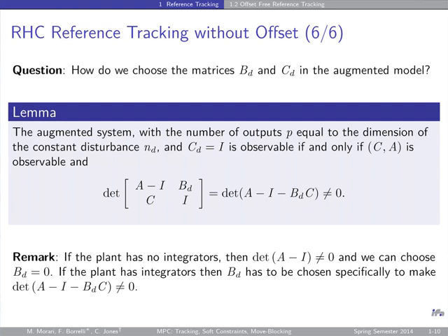The only disadvantage for some computations of this penalty function is that it has this kink, as you saw. It has a corner down there. For optimization and for software, you usually don't like those corners, okay? You don't like the non-differentiability of this function. It's easy to fix. All you do is add an additional term, v times epsilon squared, which smooths the kink. It doesn't matter how big v is, it smooths it. But it still has the u epsilon characteristic, it just doesn't have a zero slope. So you will still have the properties preserved exactly that you want, but smoothly.